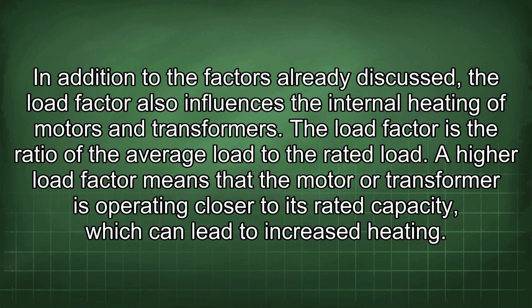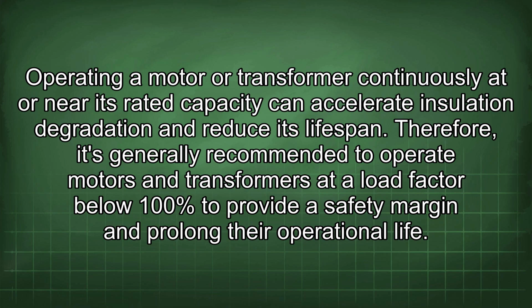In addition to the factors already discussed, the load factor also influences the internal heating of motors and transformers. The load factor is the ratio of the average load to the rated load. A high load factor means that the motor or transformer is operating closer to its rated capacity, which can lead to increased heating. Operating a motor or transformer continuously at or near its rated capacity can accelerate insulation degradation and reduce its lifespan. Therefore, it's generally recommended to operate motors and transformers with a load factor below 100% to provide a safety margin and prolong their operational life.